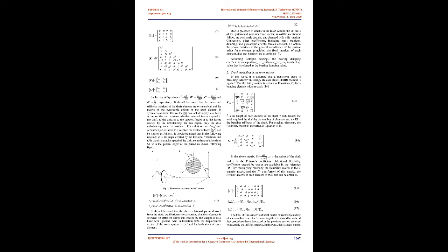The effects of crack depth on the stiffness of the shaft and the natural frequencies of the rotor system have been analyzed in a test. Natural frequencies of the system have been obtained using a hammer impact test in static conditions. Also, the dynamic response of the rotor is analyzed.